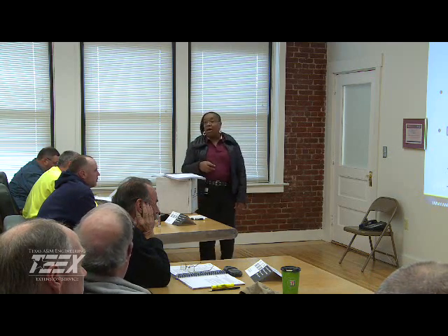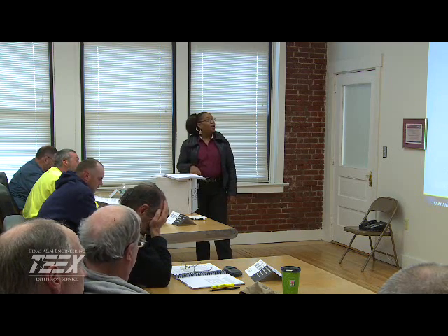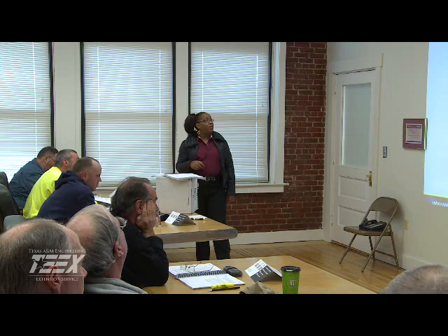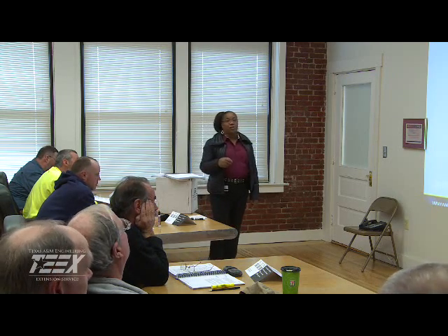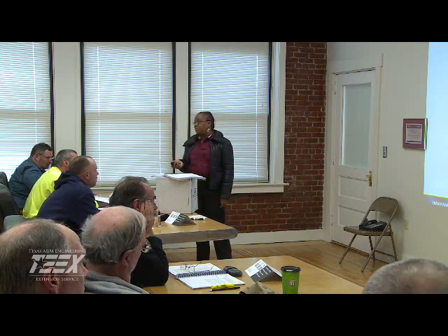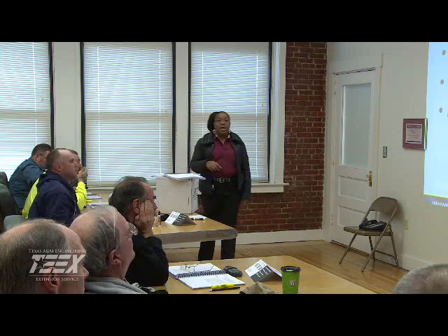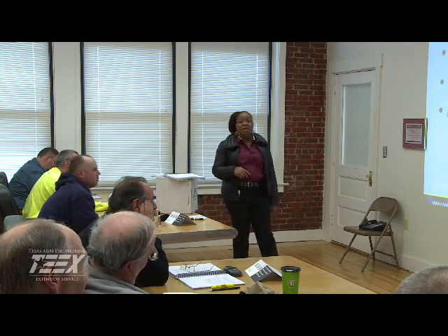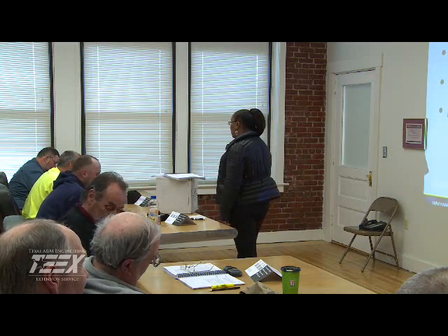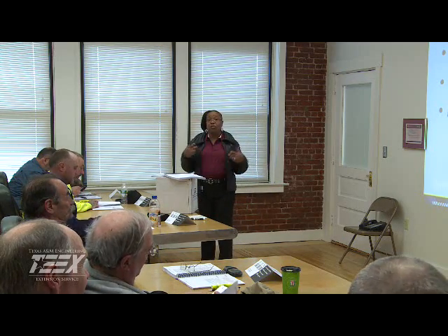Monitoring and public awareness. Again, we're going to do the indicator organism monitoring, which is the coliform group. We're going to respond appropriately to positive samples, and we're going to notify the public. Okay? And notifying the public means that if it's an acute, I have 24 hours to get that information to them, whereby they can boil their water and make the decision to use an alternate source. If it's a non-acute, 30 days to let them know something went wrong.